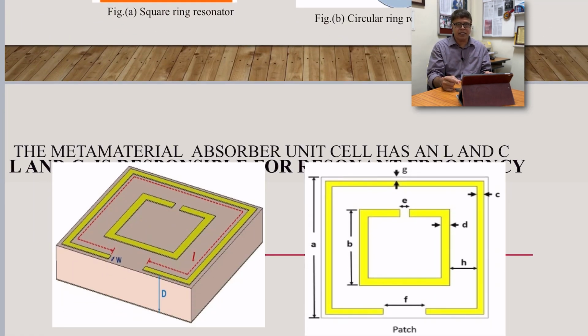Now, the same thing has been represented in this particular slide, where more than one ring is being used. It means the response of the ring resonator will be at two different frequencies, reason being two different setups of the architecture have been embedded on one PCB. So they will be resonant at two different frequencies. On a similar pattern, we can develop a ring resonator tuned to one frequency, two frequencies, three frequencies, and then we can harvest energy in multiband, so that a high amount of DC voltage can be produced. Not only with the help of multiband and combiner, we can also enhance the DC voltage by adopting the voltage multiplier circuit that we will see in the subsequent slides.